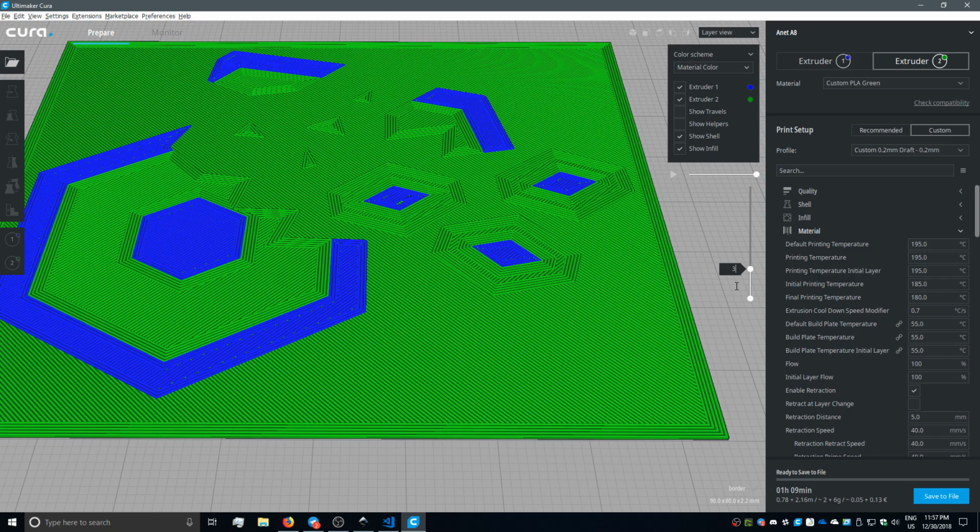What the printer needs to have enabled to be able to do this is the advanced pause feature and the filament change commands. Basically, you just add an M600 and the printer will understand. I have made dedicated videos about how to set up the filament sensor, where I explained how all of this works, and also how you can do multicolor prints with a single extruder machine. It's basically the same thing I use here.